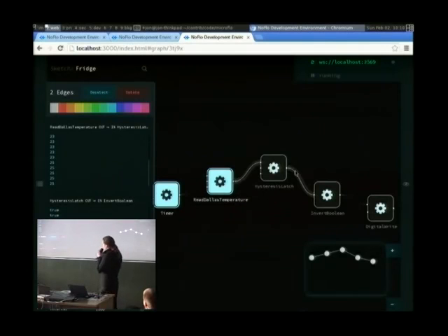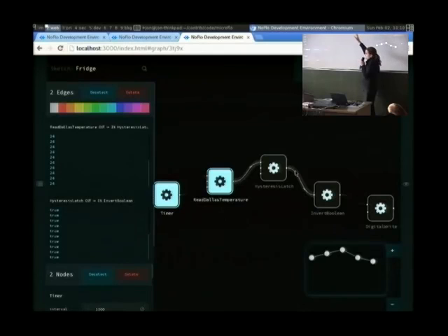So this is the program I was running on my controller. Did you see the values change? This is me observing the values of the data that's going through the program inside the microcontroller. So there's a runtime, so I can introspect it. I can say, okay, what are the values of this connection between the temperature and the latch? So if I want to know if it's working correctly or not. And these down here are the outputs. So I can determine, okay, is this hysteresis working correctly or not? And I can introspect this visually, which is quite a powerful tool.